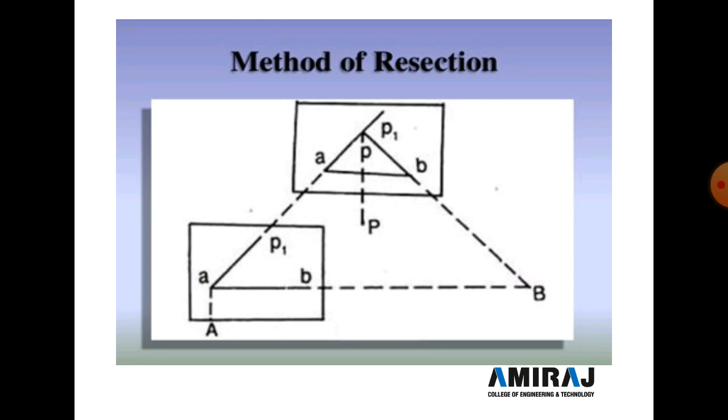We discuss from the figure. Suppose it is required to establish a station at a position P. Let us select two points A and B on the ground. The distance AB is measured and plotted to any suitable scale, like 1:1. The line AB is known as the baseline. Like, the AB distance is 30 meters, so the small ab line on paper is 30 centimeters.